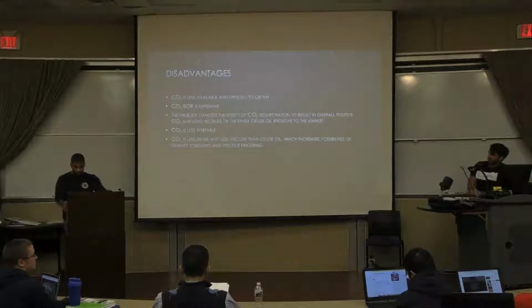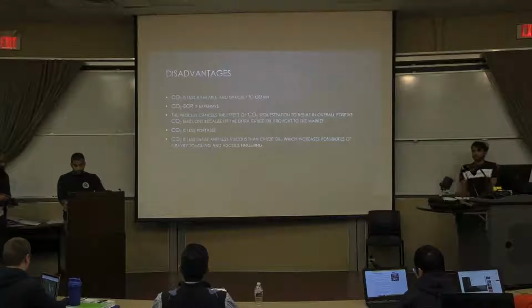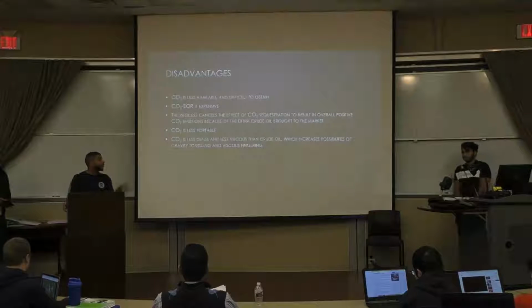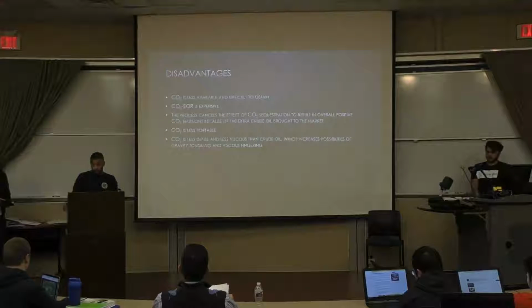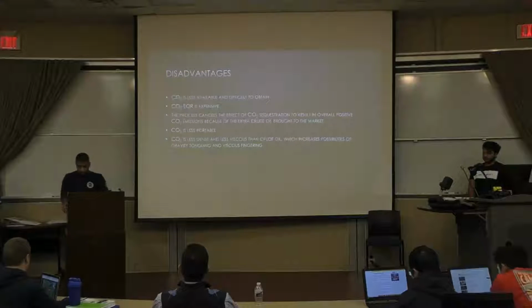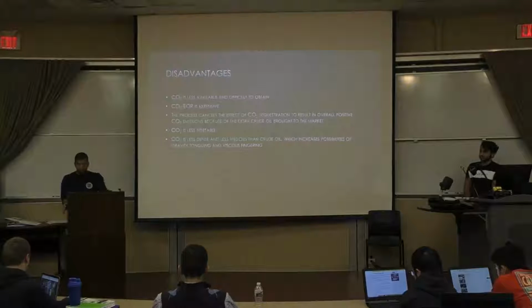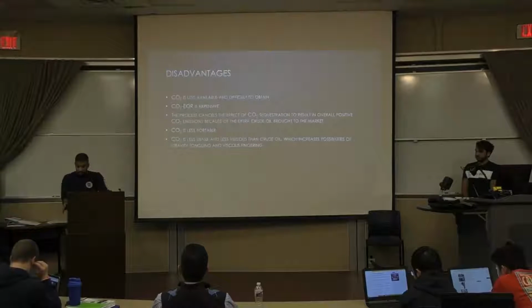However, the technique has some disadvantages since carbon dioxide is not readily available and is difficult to obtain. The carbon dioxide injection process is also expensive because carbon dioxide used for EOR is naturally extracted from underground carbon dioxide reservoirs and later transported to oil extraction plants.